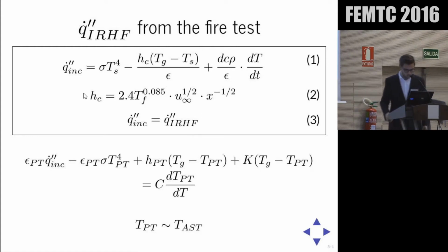equation 1 up here was formed. The plate thermometer measures approximately the temperature of a surface which cannot absorb any heat. This temperature is also called the adiabatic surface temperature. It's an illustrative temperature measure, taking into account both the radiation and convective heating from the surrounding gas.